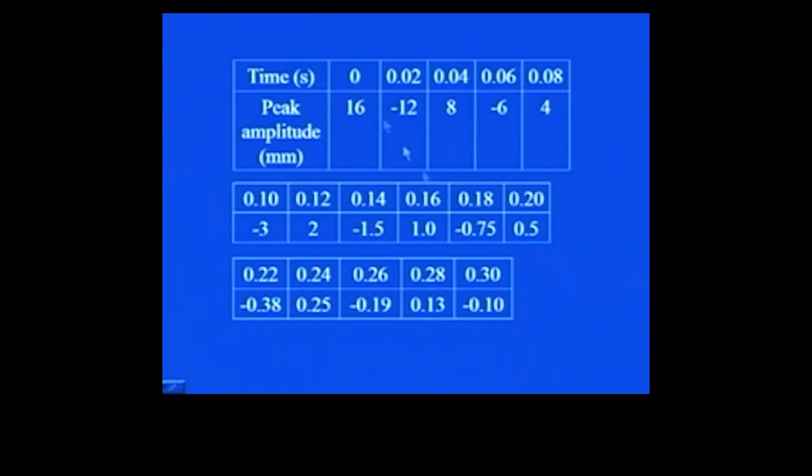is increasing from 0 to 0.3, you see here the peak was 16 mm, however here at 0.30, that is at time t equal to 0.30 seconds, you have peak amplitude of the magnitude of 0.1 millimeter only. So, you see how much is the difference. So, why exactly this difference is occurring is due to the damping which is present in the system. How can we measure that?